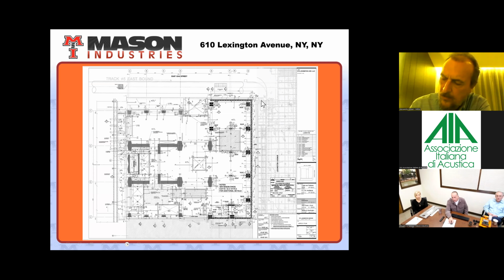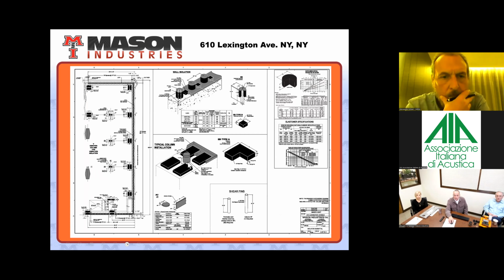And these are shear pins to handle horizontal loads. And these are column capitals that support the building itself. Shear pins are designed to handle horizontal wind loads and minor seismic loads so that there's no real significant movement because you've got mechanical systems that are working vertically through the structure as well as elevators and people movers. So it is a major issue. So we came up with the idea of shear pins many years ago to handle the horizontal load, and that's what this element is right here.